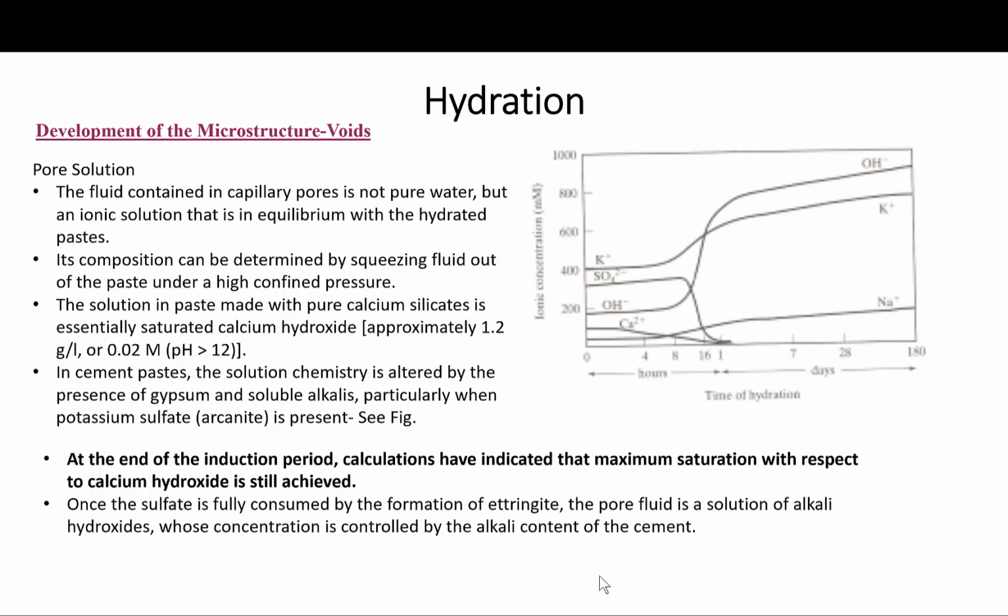So let's talk more about the pore solution. The fluid contained in the capillary pores is not pure water, but an ionic solution that is in equilibrium with the hydrated paste. This figure shows the ion concentration as time goes on.